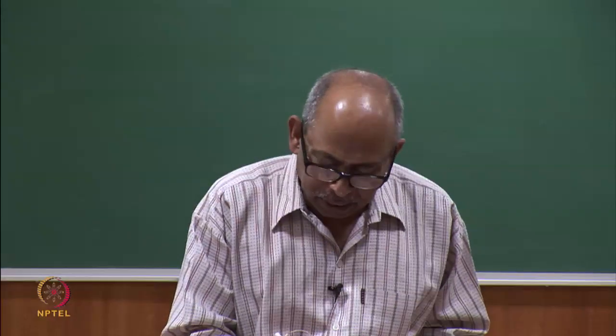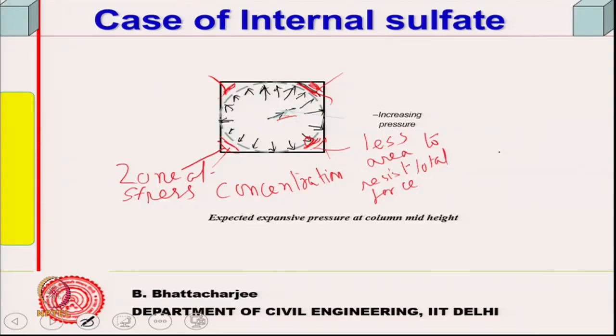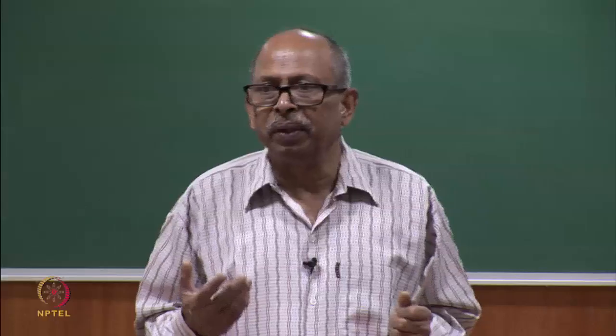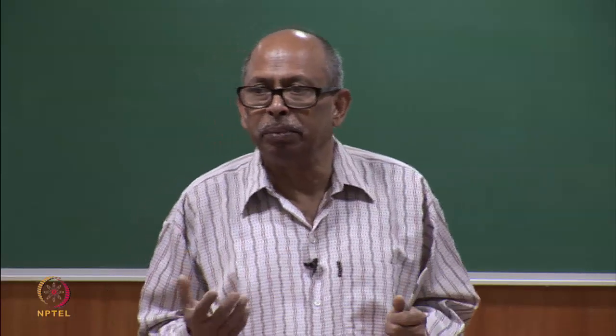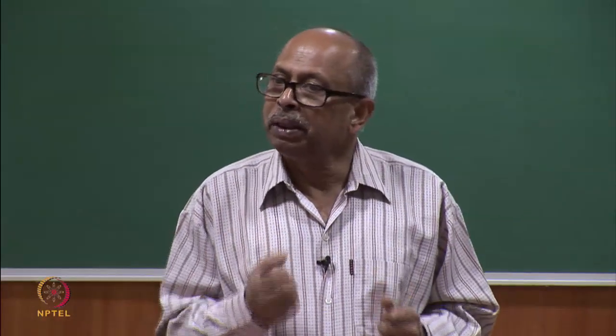Even if the pressure is there, supposing there is a rebar, it would protect, and will not allow the concrete to go away. So, leaving the rebar, the surrounding concrete has gone away, and cracks have also developed in some places like this, a vertical crack. So, this was my first conjecture. Looking at that, this must be because of some internal pressure.